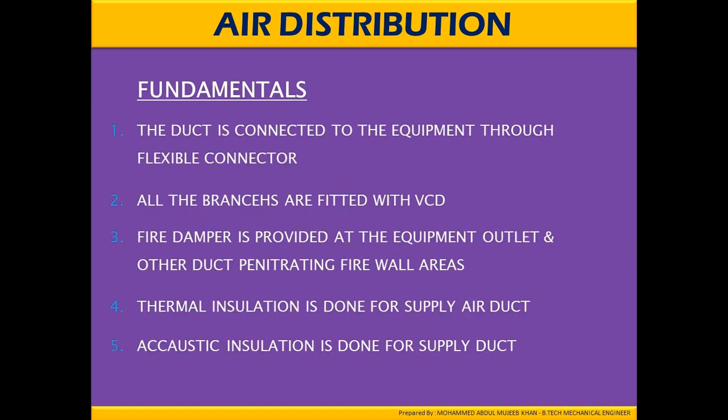The duct connection to the equipment through flexible connectors. All the branches are fitted with VCD, volume control damper. Fire damper is provided to the equipment outlet and other ducts penetrating firewalls areas. Thermal insulation is done for supply air duct. Acoustic insulation is also done for supply air duct.